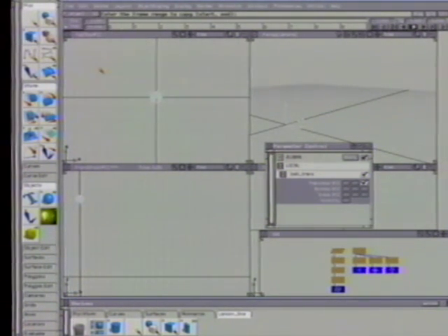Now go to the Edit menu and select Copy Keyframes. Enter 0 and 10 to copy the keyframes at frames 0 and 10. Next, go to the Edit menu and select Paste Keyframes. Type 20 to place a copy at frame 20, 4 to make 4 copies, and 10 to specify the gap between the copies. Press the Enter key.